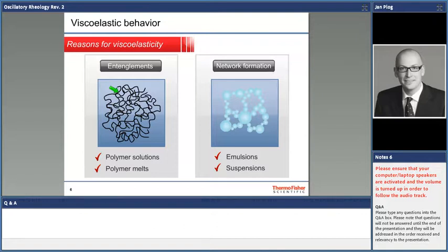When you have, for instance, something like a shower gel or so, which behaves too elastic because your polymer might be of too high molecular weight, your end customer, be it the processing people that have to fill that stuff into bottles, or the actual customer that buys your product in the grocery store, will feel that elasticity. Okay, in the filling process, when your shampoo is too elastic, you will see stringiness.